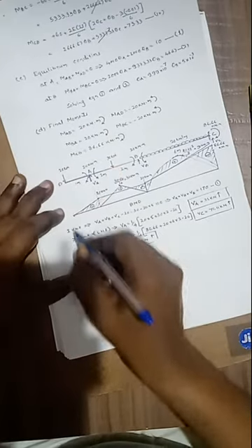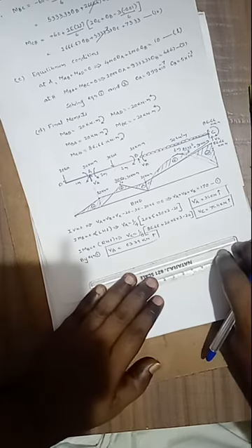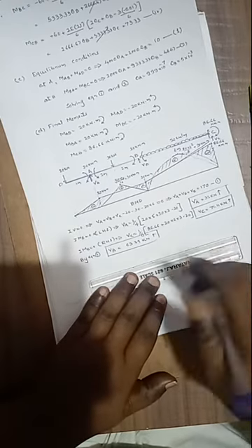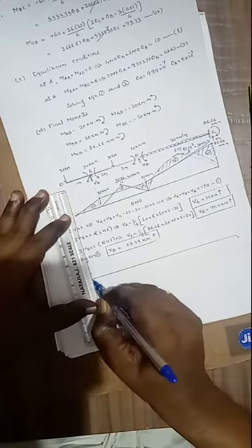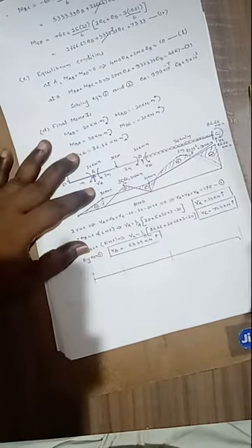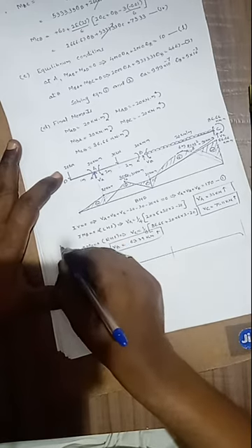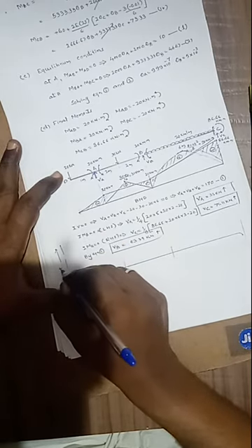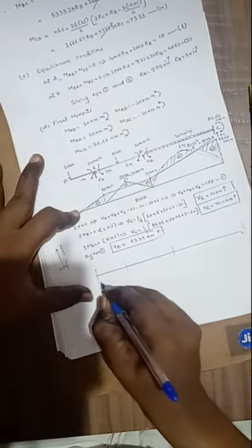Then to draw the shear force diagram for this one, we will consider this as the reference line. Here this one is the ordinate. Extend these lines below the support. Start from the left. In the left portion there is a downward force. As per the sign convention of shear forces, left upward is positive. Coming from the left portion, the net force is downward, that is 20 kilonewton.